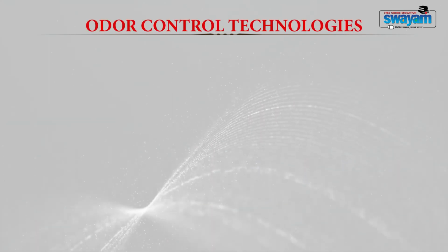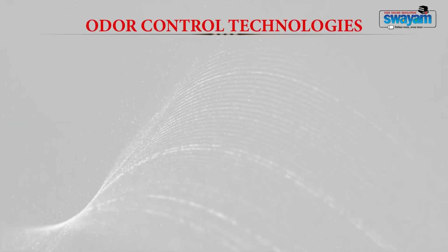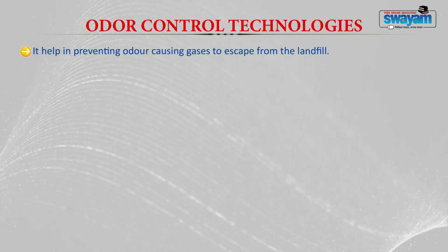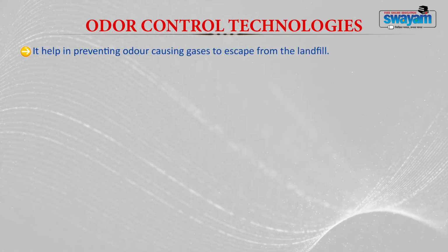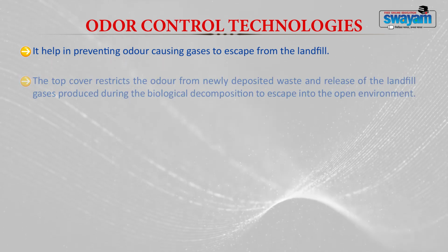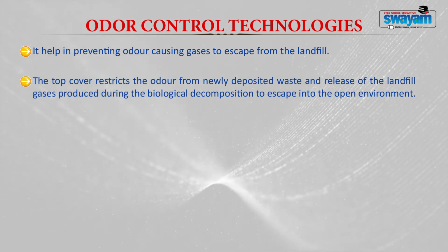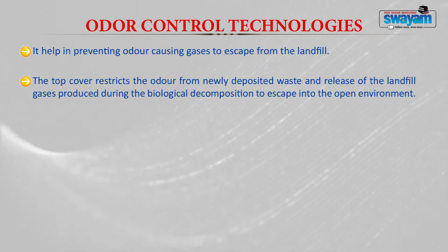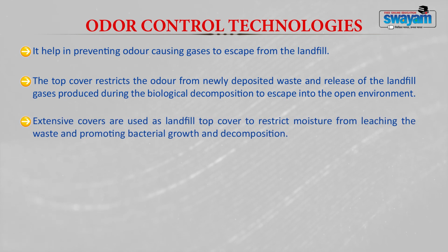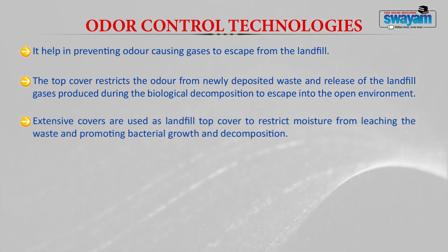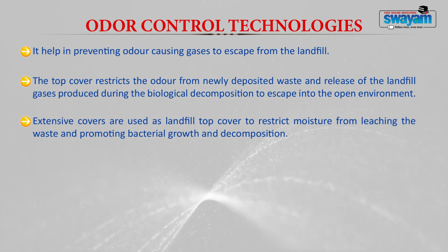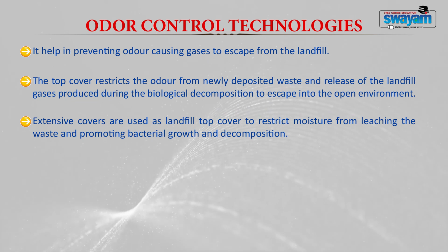The last method of gas treatment is odor control technology. It is generally used to prevent the odor that is generated during the gas escape from the landfill. The top cover restricts the odor from being released out of the landfill into the open environment. Extensive covers can be used to restrict moisture from leaching into the waste and promote bacterial growth and decomposition, because the gas is generally generated during this process.